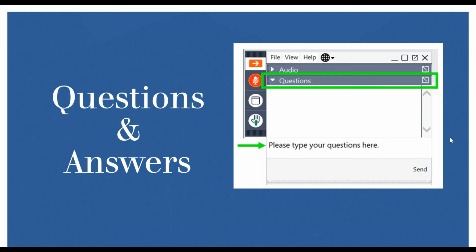Okay, there's a general question here, but I guess we will answer that. I'm not sure on the strokes requirement for the toxic tubes. Kindly advise the guideline. Actually, I can just answer this straight away. All the Dräger tubes' instructions for use indicate the number of strokes, and in fact, on the tube boxes, sometimes they give us some guidance. So every pack of Dräger tubes comes with the instruction for use, and with that you can also take note of the number of strokes required. And I think the tube itself also indicates the number of strokes required. Yes, I think that is correct.